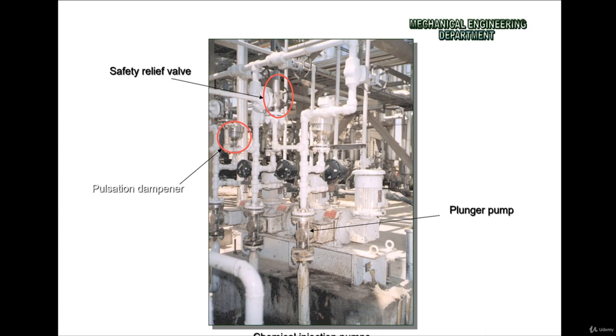Every type of these pumps has this, the real one may have more than one pump on one common skid. You see this is one skid, and this is 1, 2, 3 pumps. You can split the flow on 2 pumps or 3 pumps, depending on how much flow. So this is a suction, and this is a discharge, and this is the diaphragm. This moves the plunger, and it's moving the fluid.